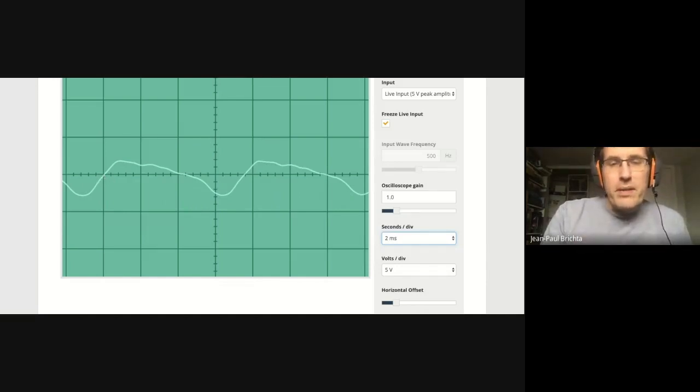So if I start it there, then I can count: 1, 2, 3, and not quite 4 major divisions. So I have 3 and 4 minor divisions, and each minor division is 0.2 of a major division. So in other words, I have 3.8 divisions, and my seconds per division is 2 milliseconds.